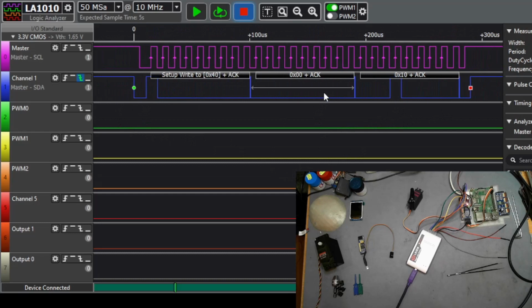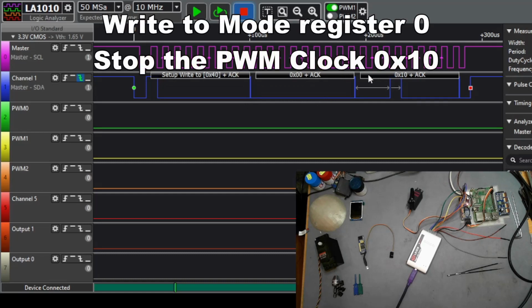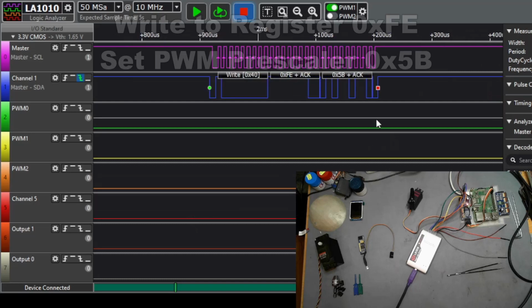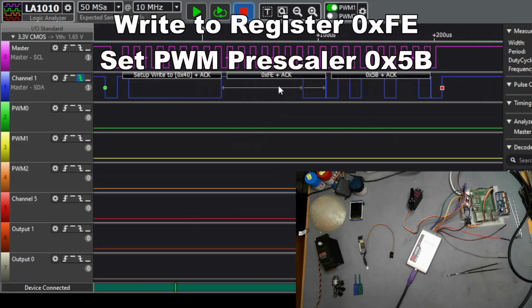So the 0 and 10, the PCA hadn't been used at that point, so the Raspberry Pi service, or the PCA service, actually configured the hardware device, PCA 9685, and configured it to reset and start up. After it completed the reset and start up, it then selected the register FE and then proceeded to write some data to it, which is the clock frequency.